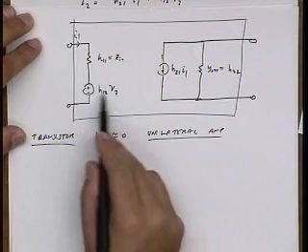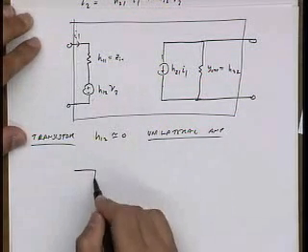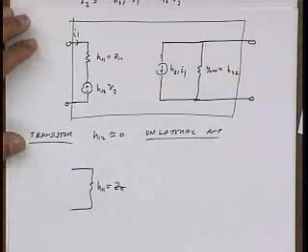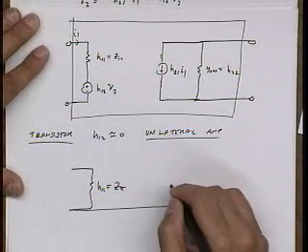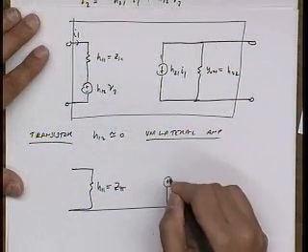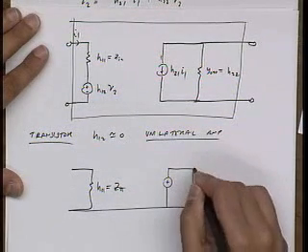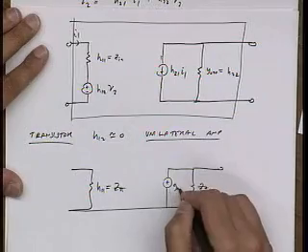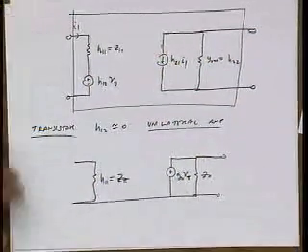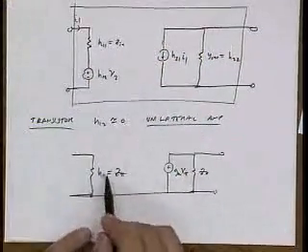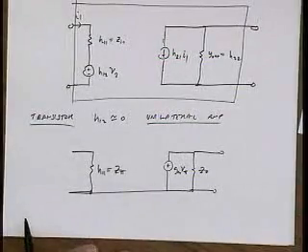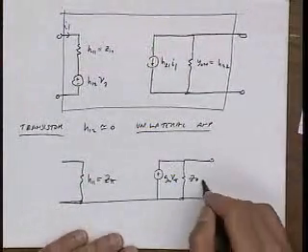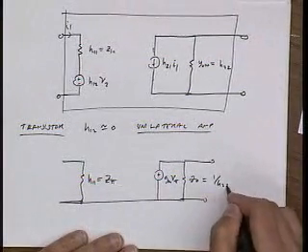So if H12 is equal to 0, then this is just the input impedance, right? So H11 is actually Z pi. Beautiful. Okay, in fact, I'm going to just draw. Let's call this Z out. Let's call this GM V pi. So clearly H11 is Z pi. Okay, how about H22? H22 is just the impedance looking in here. So this is equal to 1 over H22, right?